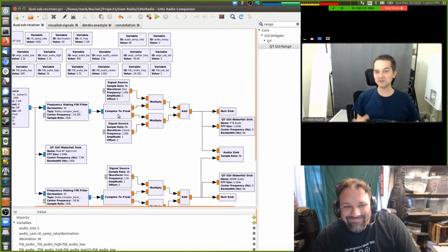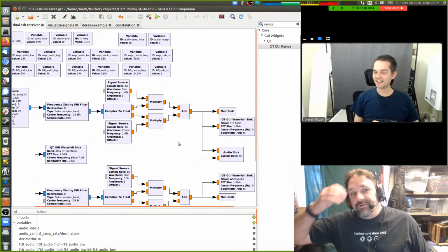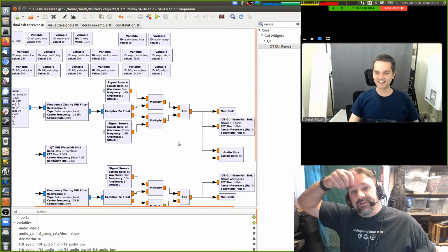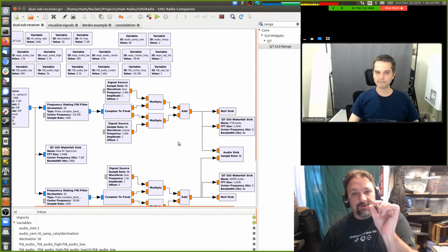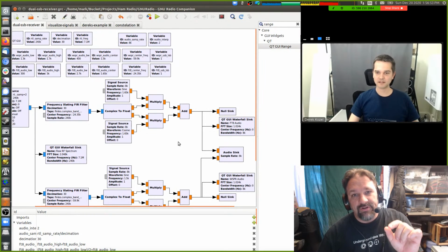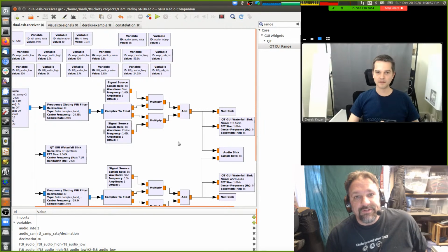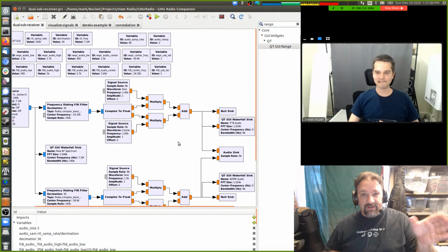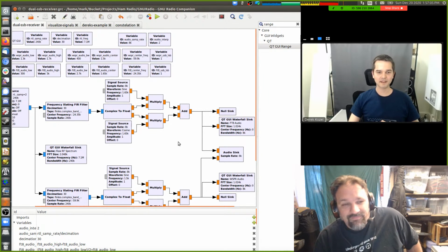Somehow, you have to phase shift the entire range of audio frequencies by 90 degrees for each frequency. Yeah, which is why that's a pain in the ass to do. You can do it with a very narrow band signal, like with the QCX. Actually, I've been looking at it. It's a very narrow band audio receiver, and so he's able to do a 90 degrees phase shift on that very narrow band of frequencies, and it actually works out reasonably well. Trying to do it on 300 to 3000 is a lot more complex.